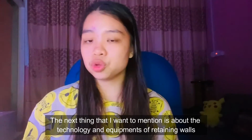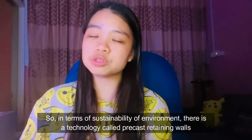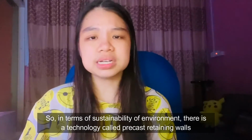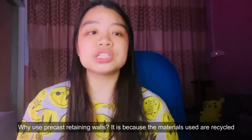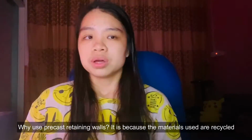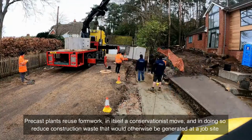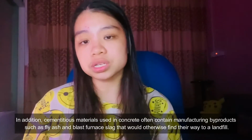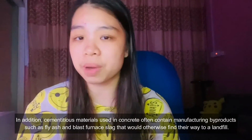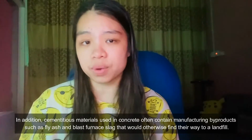The next thing that I want to mention is about the technology and equipment of retaining walls. So in terms of sustainability of environment, there is a technology that is called precast retaining walls. Why do they use precast retaining walls? It's because the materials used are recycled. Precast plants reuse formwork, in itself a conservationist move, and in doing so reduce construction waste that would otherwise be generated at a job site. In addition, cementitious materials used in concrete often contain manufacturing byproducts such as fly ash and blast furnace slag that would otherwise find their way to a landfill.